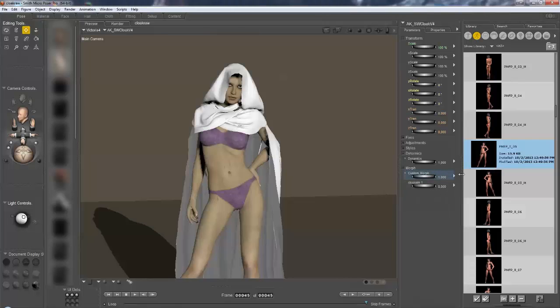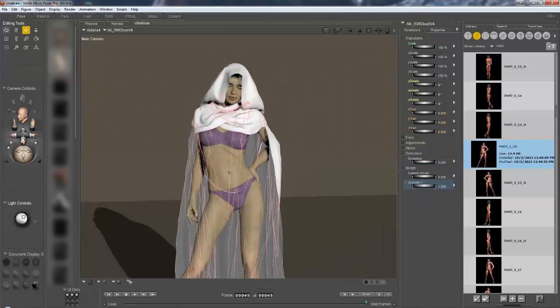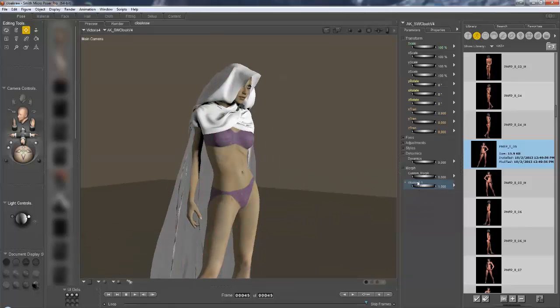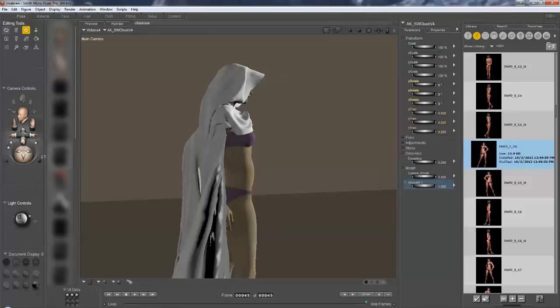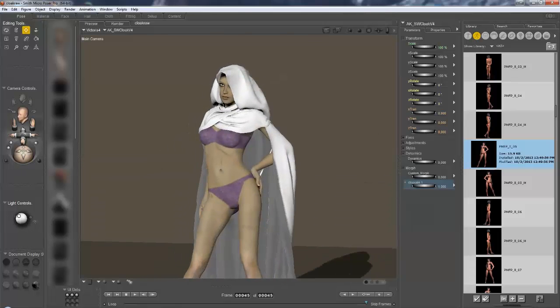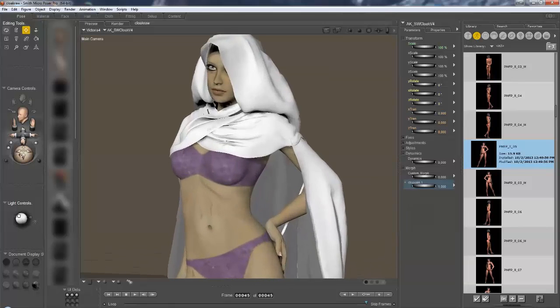You're doing the same thing here. Zero out the dynamics, zero out the custom morph, enter value 1 for your new morph. Now at this point sometimes Poser duplicates this and you get a very distorted shape, so you have this object export and import option as, I will say, a backdoor.